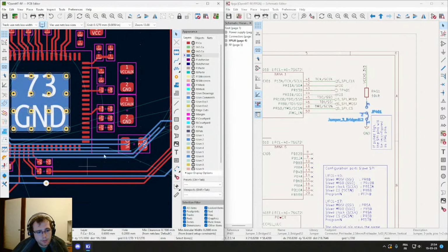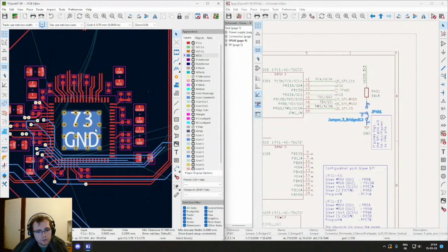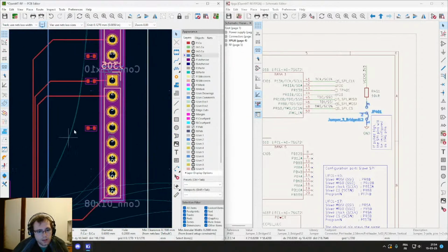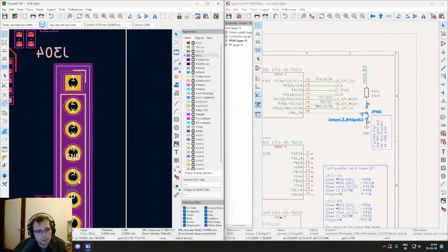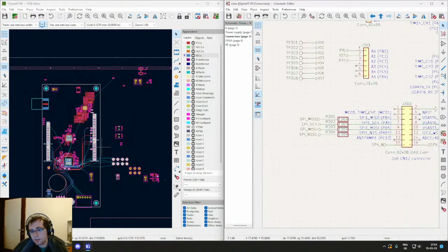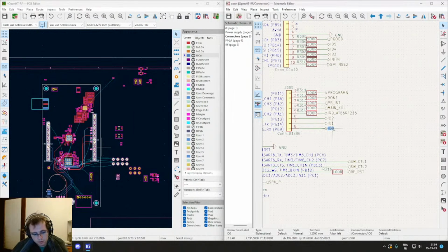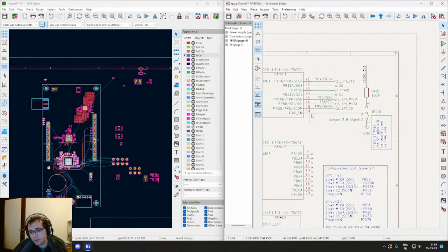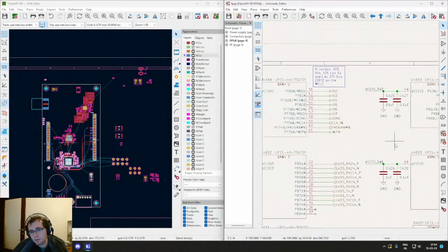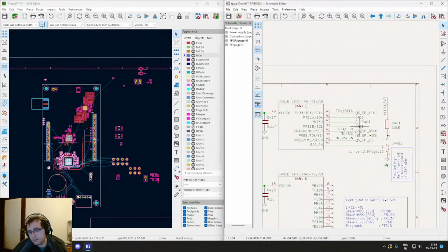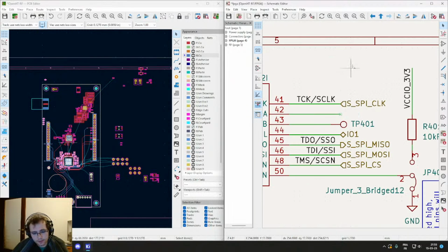This signal, which is on top of all our signals, will need to go as high as possible. It's IO0, and so we are going to exchange IO0 and IO5. So leave the sheet connector IO0, or maybe we'll do that on the FPGA sheet. Can we do that? Oh yeah, it's not very important anyway. IO0 and IO5.